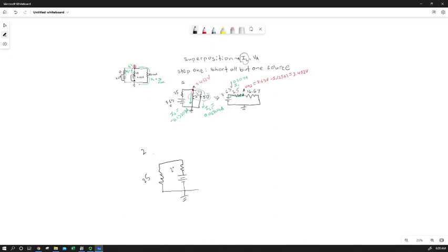25 ohms, 25 ohms. And in case you haven't noticed, sign convention is everything. Understanding which way things are flowing and which way voltage is dropping or rising versus ground is key to making these techniques work. So here's our node A. And we have the same kind of series parallel, except it's in a different place. So this is, again, equivalent to the same kind of series parallel, but everything's in a little bit different place, and that makes all the difference.